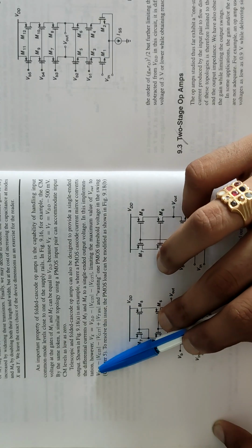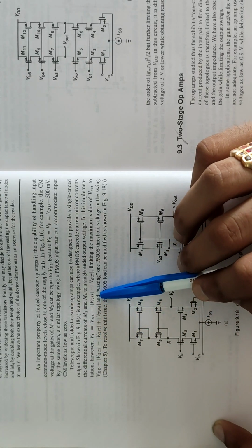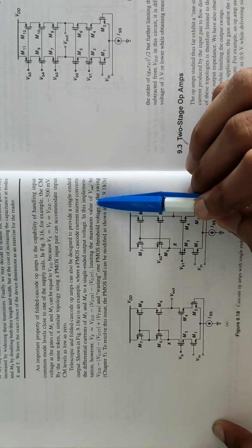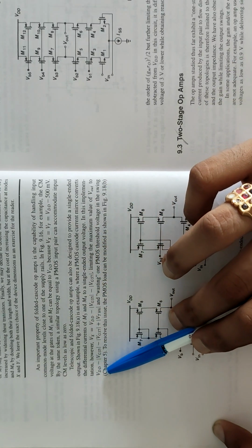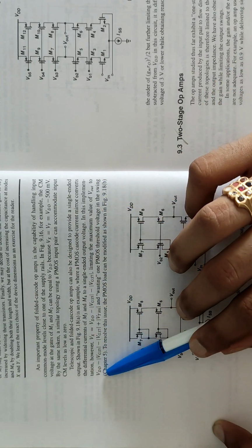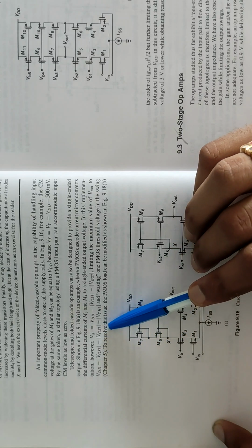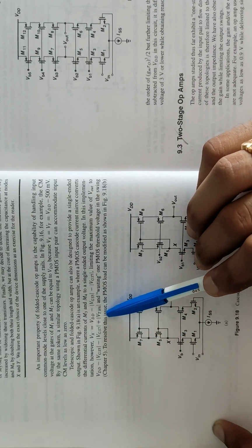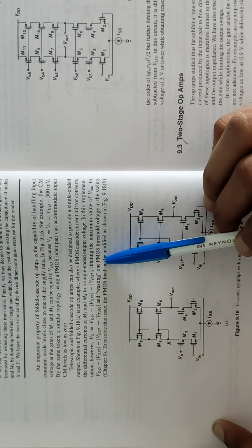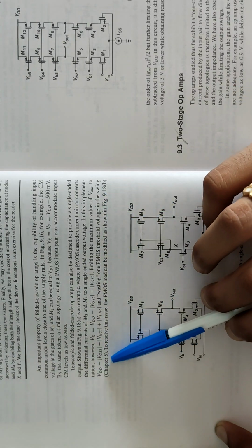In this implementation, however, Vx equals VDD minus VGS5 minus VGS7, so the output swing is limited to VB minus |VGS5| minus |VGS7| plus VTH6, wasting one PMOS threshold voltage in the swing.